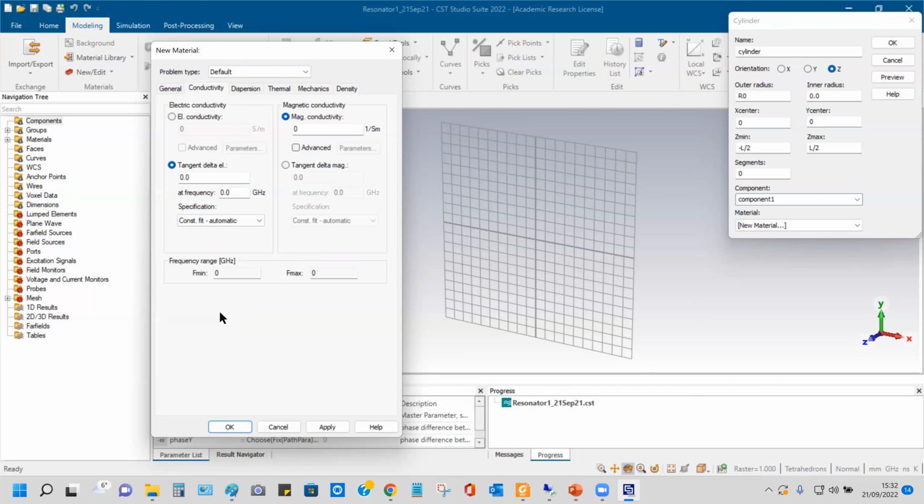But it will have a certain conductivity, that is, how much free electrons you are finding. Based on that only, the tan delta is calculated. So according to the dielectric, it is a loss, right? It should be a kind of insulator, but it is not behaving as an insulator to a certain extent, a small extent. It is conducting also. So that's how the tan delta is defined.